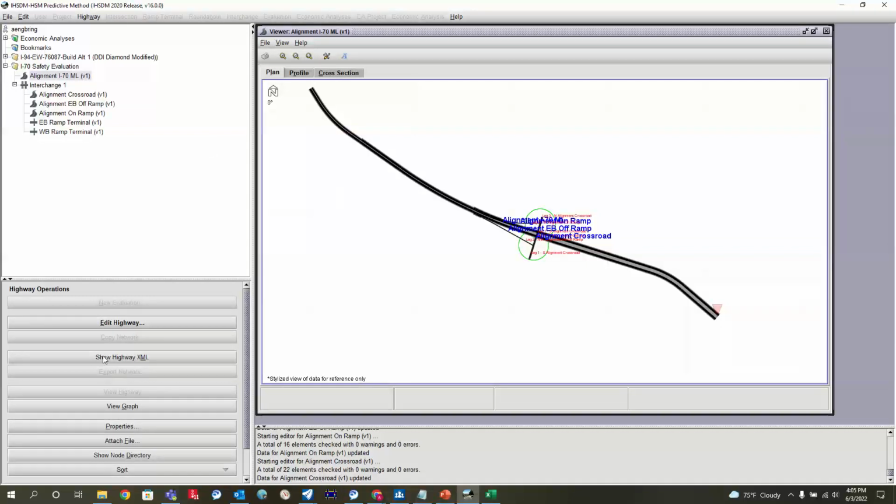How it does that is there is a thing called a CMF, which is a crash modification factor, and there are crash modification factors associated with all sorts of these inputs, such as lighting, your lane widths, shoulder widths, median barrier, outside barrier, median width, non-traversable median, horizontal alignments, vertical alignments, horizontal curvature.